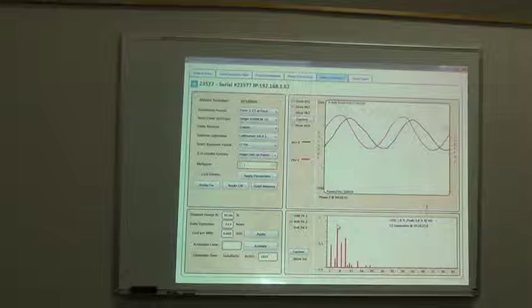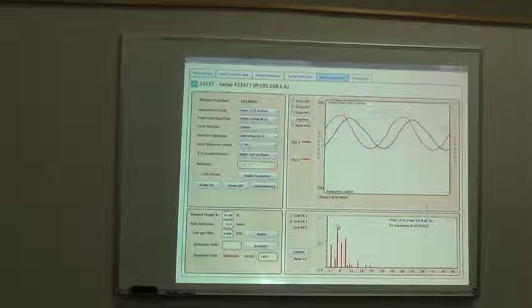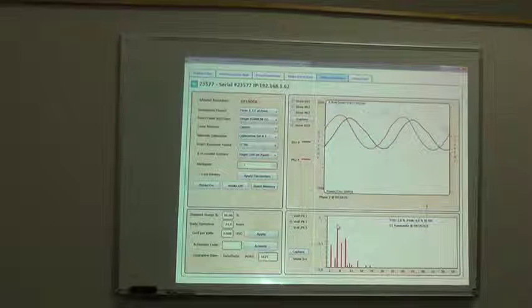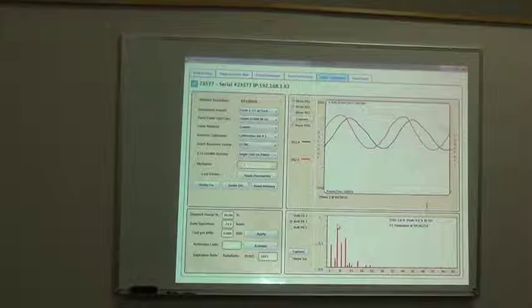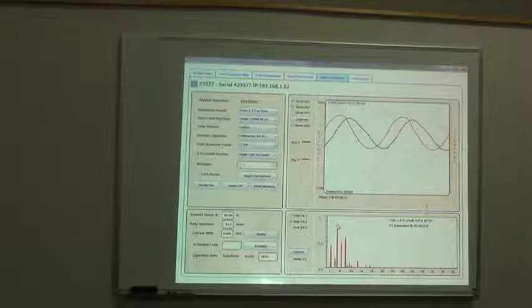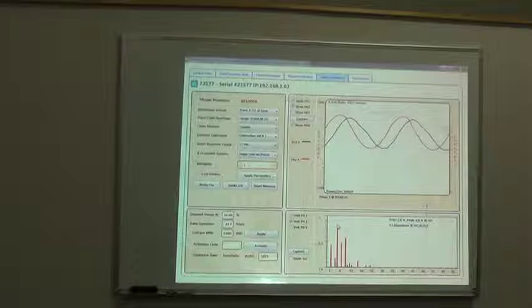Because it was so loud, they all had the headsets. Was this motor on a drive? Just a speed drive? No, it was not. See, that makes the bearing problems worse, because high frequency noise current runs through the ground, gets into the bearing, and flutes the bearing out, and that causes failure quicker. And then the imbalance makes that problem worse, so the SP1000 would help reduce that problem. Well, let me tell you this.